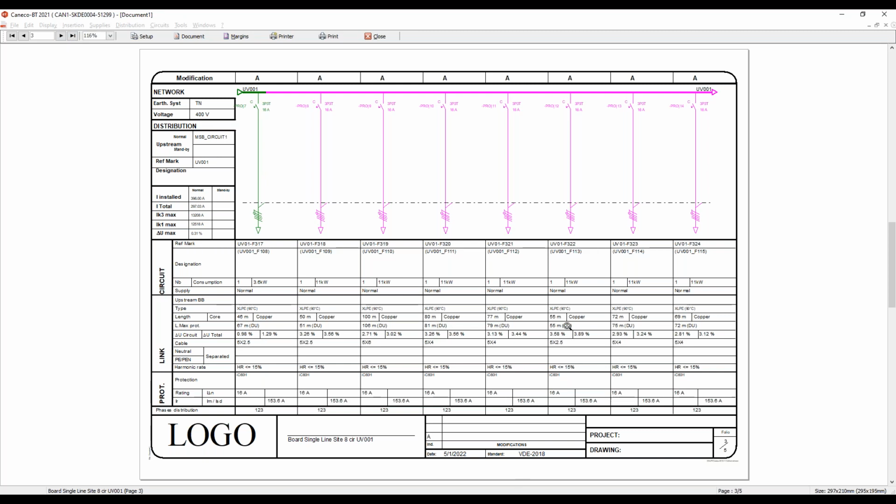Just go to the next one. It's a bigger failure. So here we are quite near to our drop down voltage of 4%, which we have adjusted in our software. So I don't know where all of you are located. But this is just to define clearly on which position you are and what type of fuse you need to use based on the power consumption, based on your standards, and you can calculate it in the way you need it.